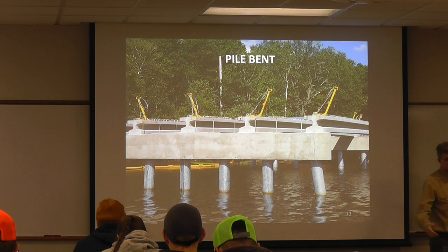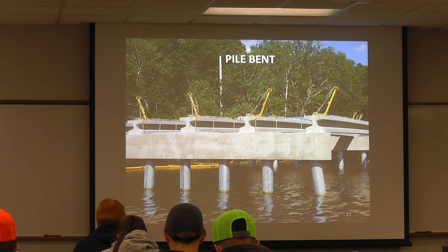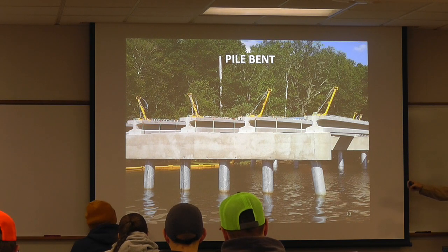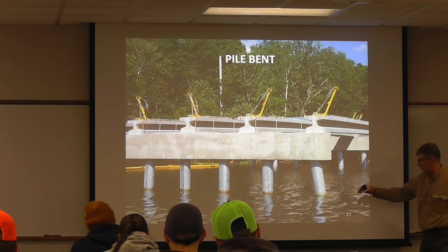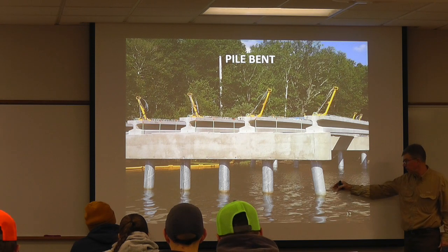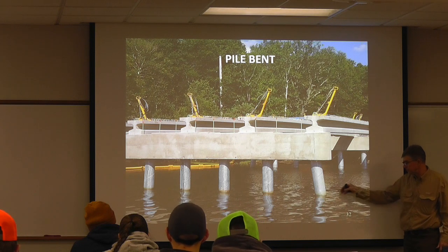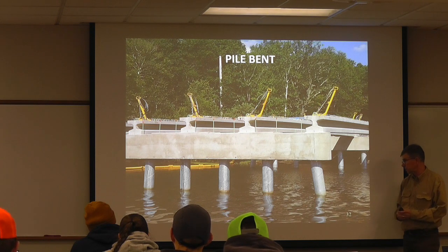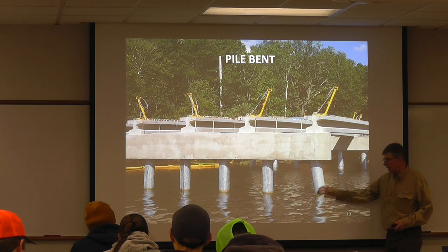And I've seen several bridges that are constructed that way, because it is a lot easier. If we did a conventional pier, like a hammerhead pier or a fixed pier shell, you'd have to dewater it.